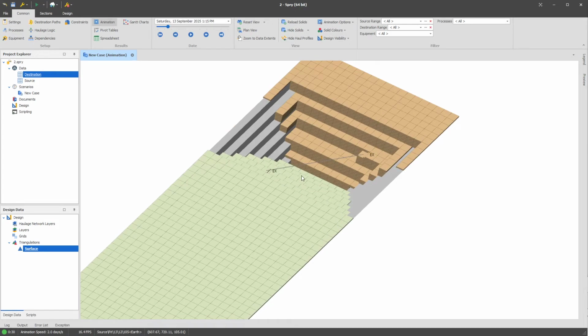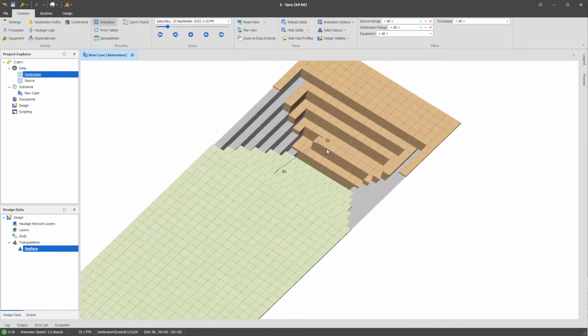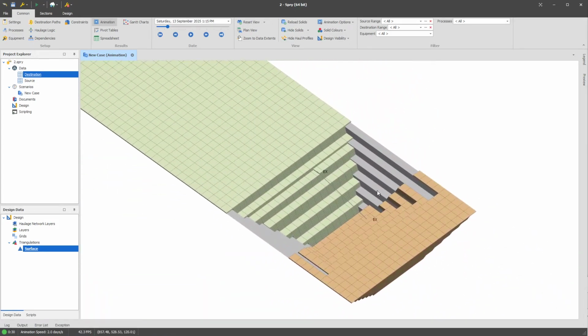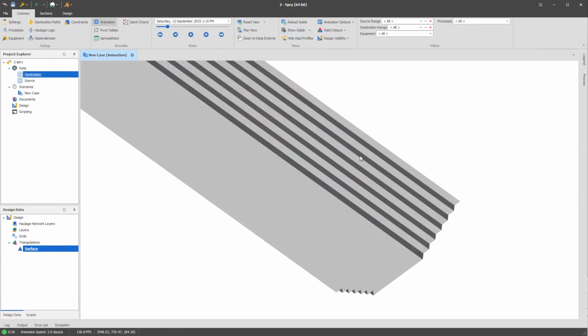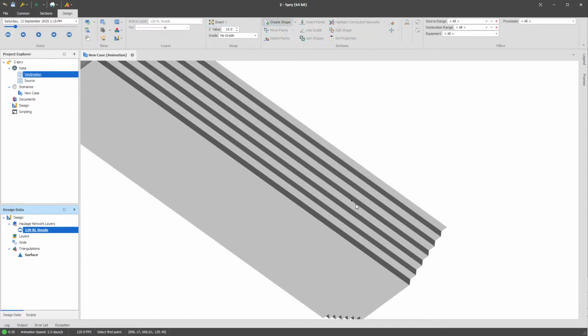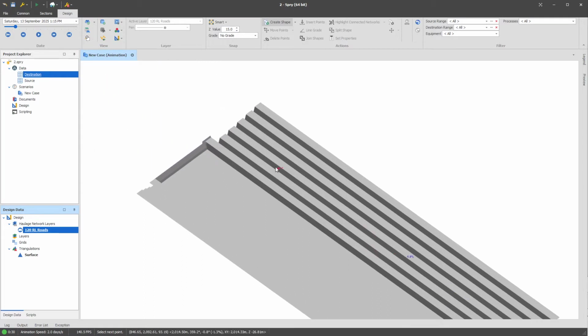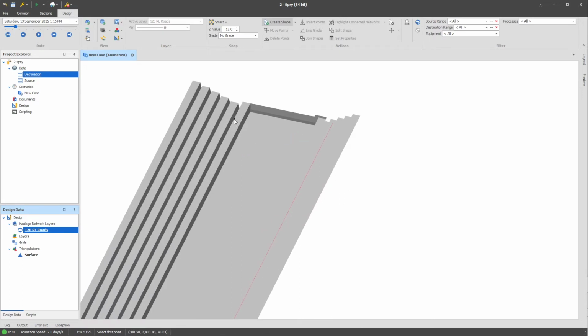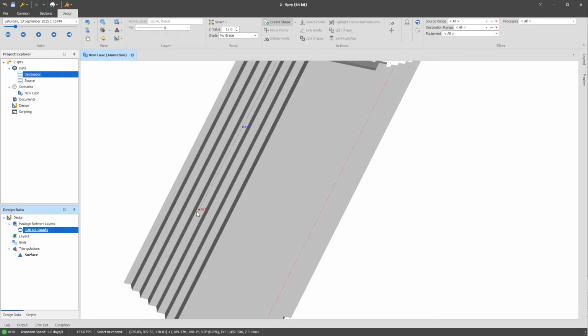We're going to start by generating the roads that head along the middle of this pit. I'm going to define that the roads sit at this 120 RL for this particular exercise. So let's go to our roads, get a design, and create our shape. We've got the nice little smart snap now, and it's just literally going to run because my road is nice and simple. I tried doing something a little bit more complicated and I couldn't work out how to do it without a design package, so I just decided to do it like this.